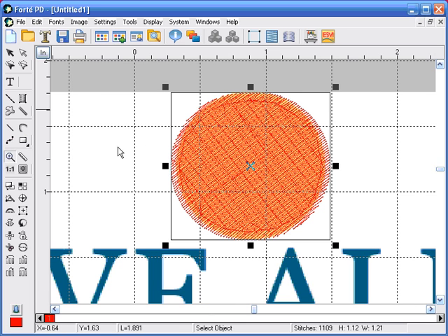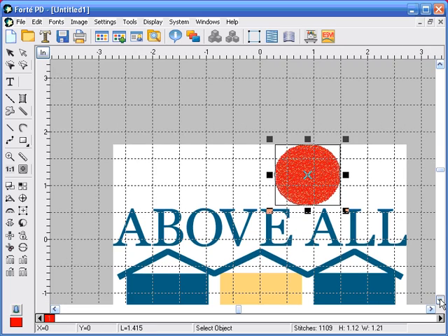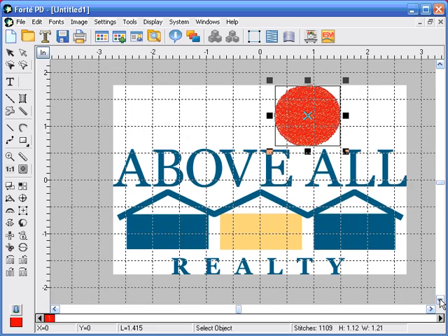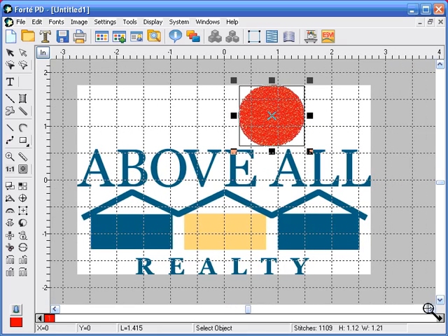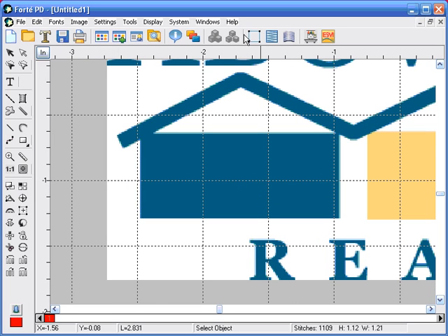Okay, we're going to zoom out, right-clicking with the zoom icon. And we'll zoom in closer to the first house. We're going to go back to the wireframe display. Select the complex fill in the straight line. And we're going to start making a rectangle shape, starting in the upper left-hand corner. Left click. You can hold the Shift key to get a straight line.